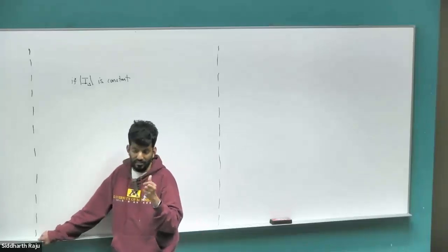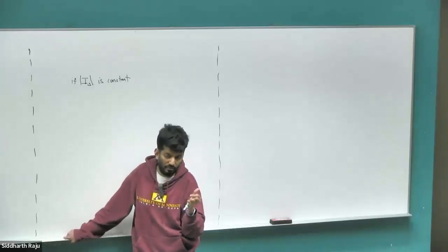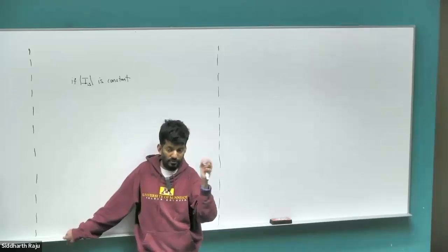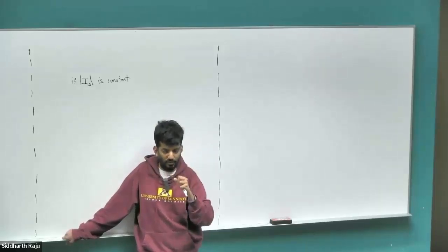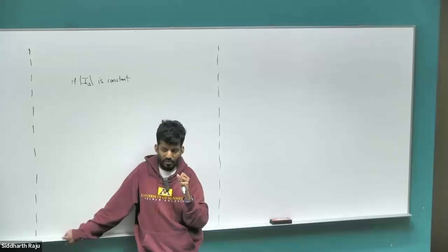So we can still design it like when we do V by F control in the beginning of advanced electric drive, we do account for the varying electrical frequency and still design a controller, but the performance of the controller will be very poor compared to what can be achieved otherwise.